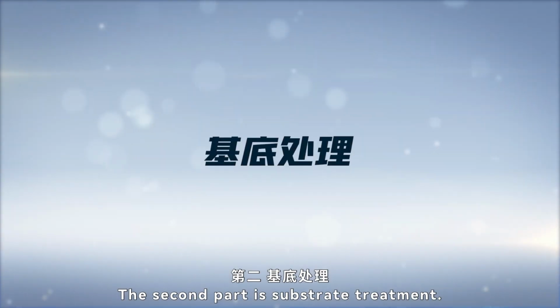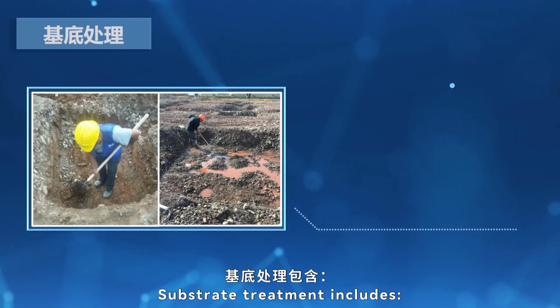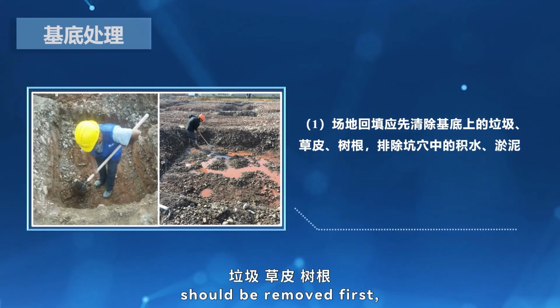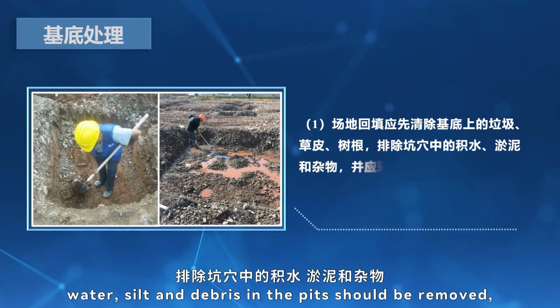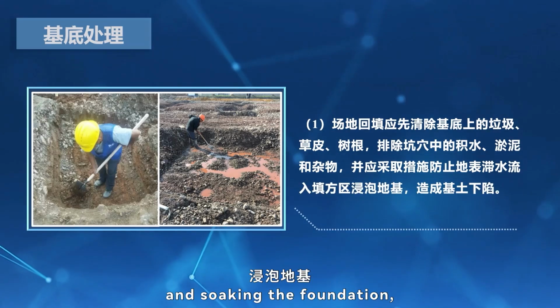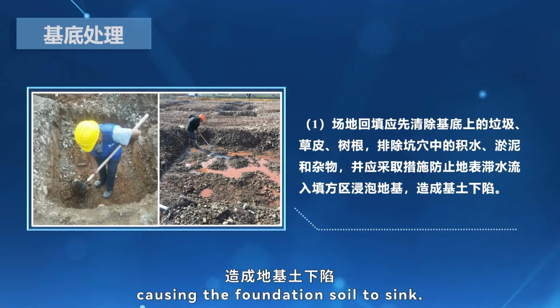The second part is substrate treatment. Substrate treatment includes: 1. For site backfilling, the garbage, turf, and tree roots on the substrate should be removed first. Water, silt, and debris in the pits should be removed, and measures should be taken to prevent surface water from flowing into the filling area and soaking the foundation, causing the foundation soil to sink.